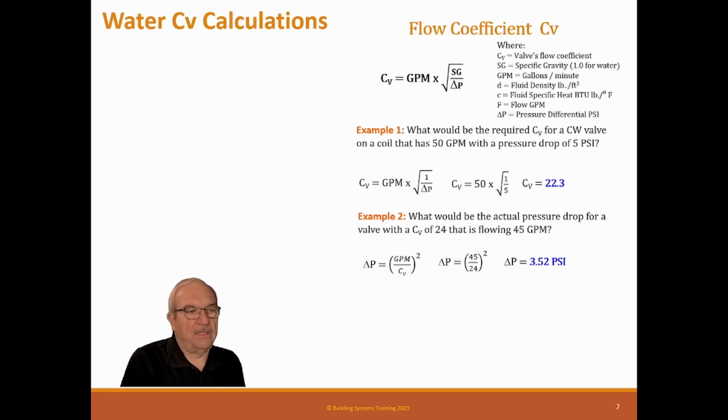Because you realize that we need to size control valves with CV, but we also need to size balance valves with CV, because a control valve is controlling the flow and a balance valve is controlling the flow. They're both control devices, so the balance valve needs to be selected properly. And why that is, I've had jobs where the engineer specified that we can't use any valve under 3/4 inch.